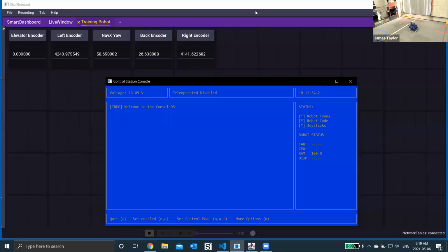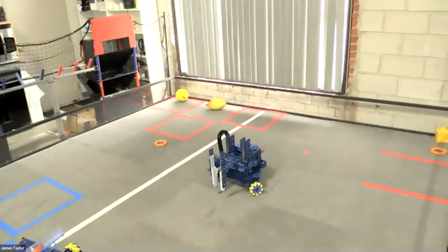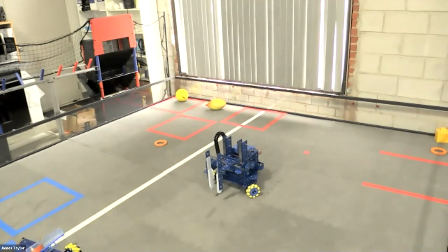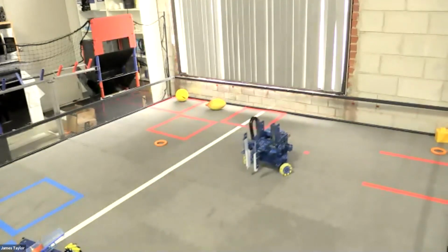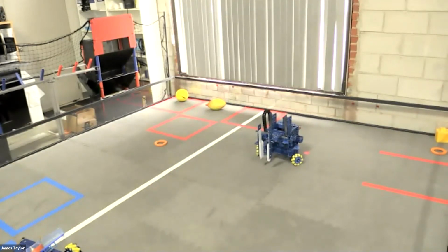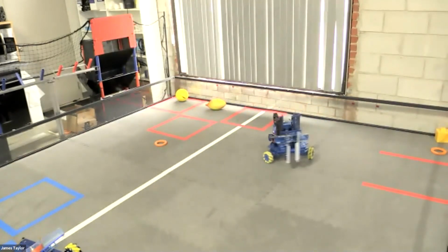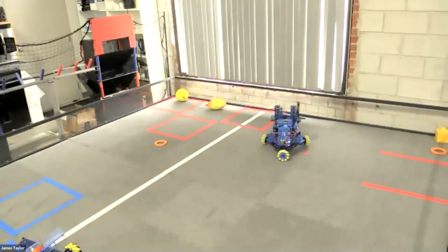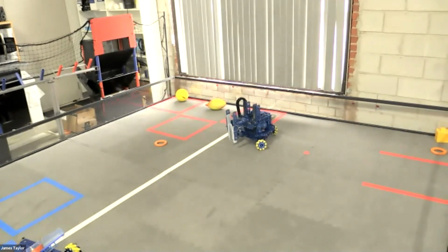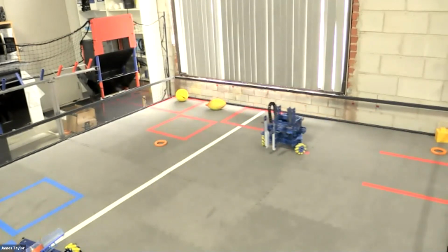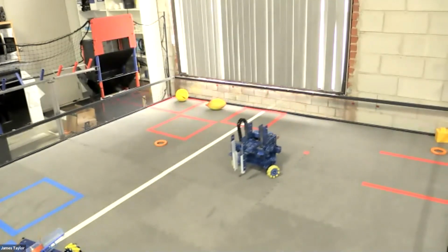I'm now going to go back so you can see the robot. Get it enabled. When I move the left joystick in the forward direction, you can see the robot drives forward. When I go in the back direction, it drives backwards. If I do the X direction on the right joystick, which is what we made for the Z axis, you can see that it just rotates. If I use the X axis on the joystick, I can drive in a sideways motion.